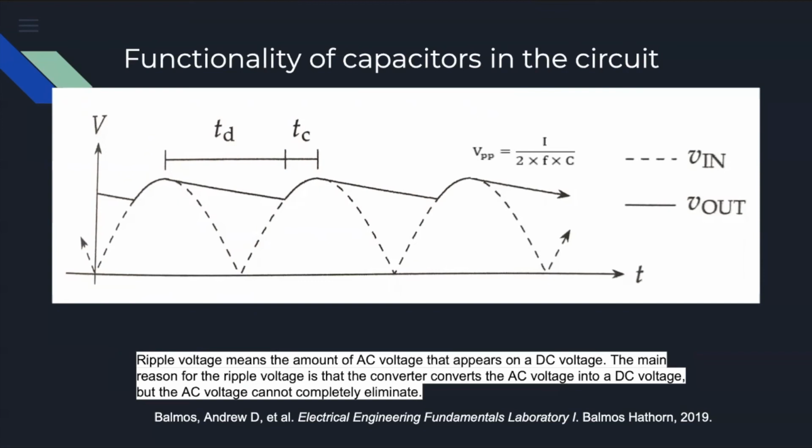The filtering stage of a power supply circuit smooths out the ripples in the rectified DC to produce a smooth direct current that's suitable for even the most sensitive of circuits. Filtering is usually accomplished by introducing a capacitor into the DC supply circuit. Here, the capacitor is simply placed across the DC output. This is because of the capacitor's ability to store charge when the circuit load does not need it. Hence, the capacitor filter is used for smoothing and reducing the ripple content in the output waveform.